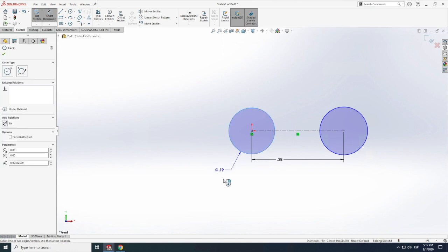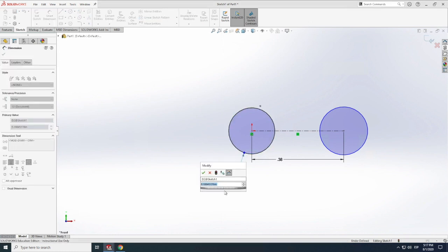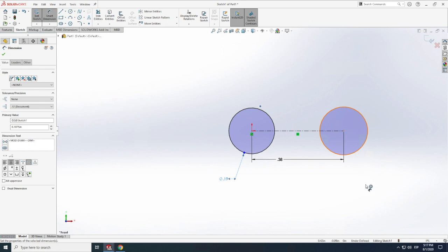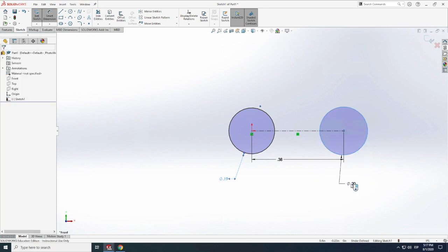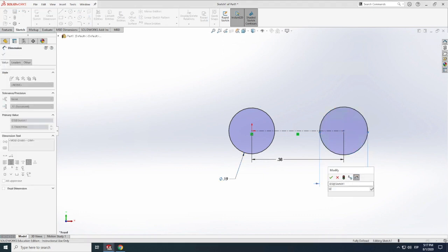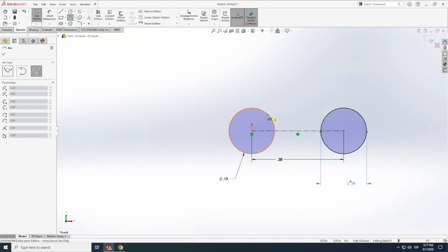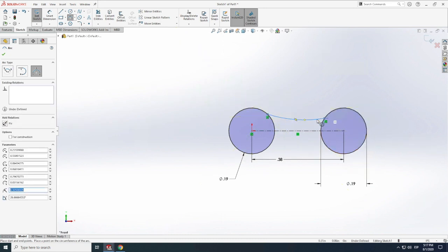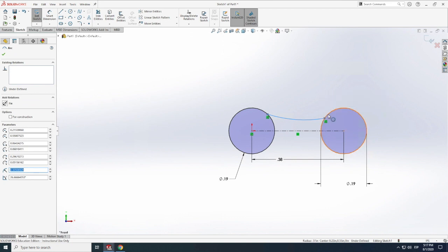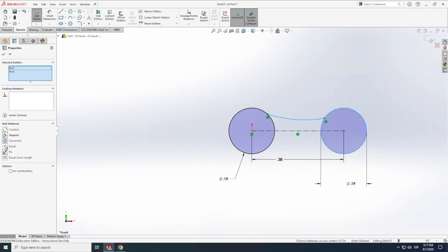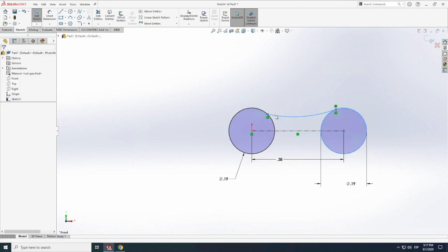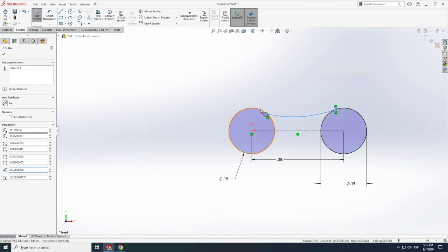In my case, I'm just doing the number 35 gear, but feel free to choose any gear of your choice, this method should be similar. I'll do the same in here, so 3/16. And now we'll do an arc in there, but here's a catch, right? We'll click in there, we'll also click in there, and we'll click in tangent. And let's do the same thing over here.